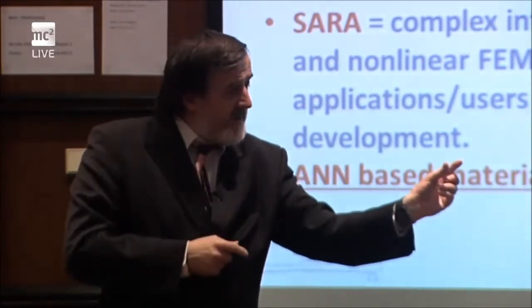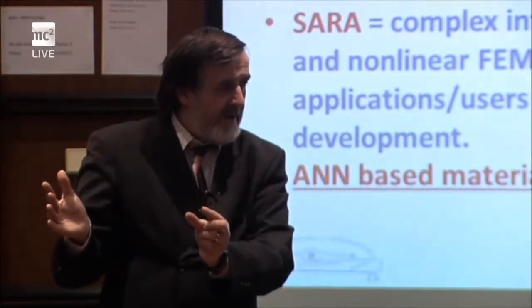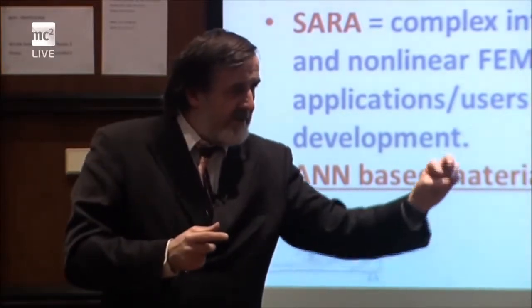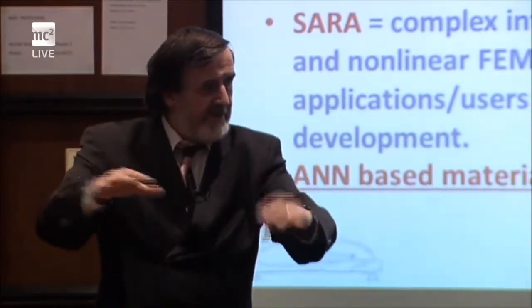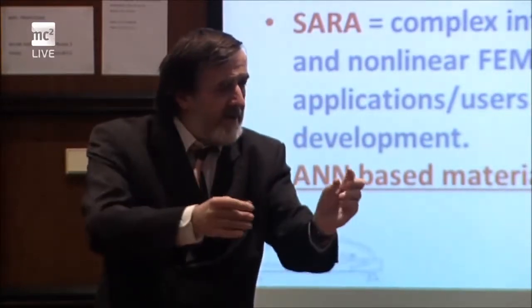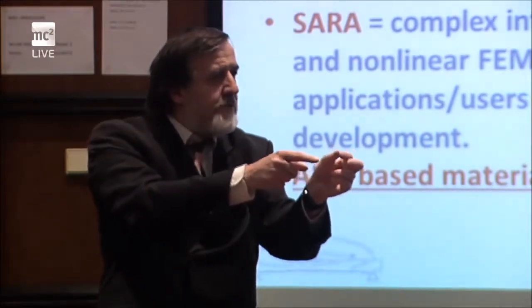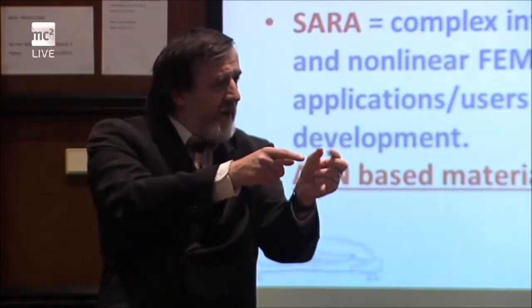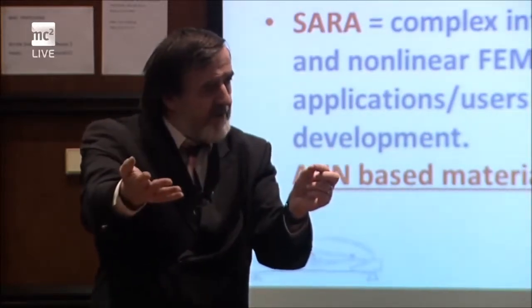If we take, let's say, the nominal value of stiffness, so there is an undamaged structure. And now these stiffnesses we change randomly to imitate so-called damage. If I change the stiffness somewhere in the beam, it's supposed to influence eigenfrequencies and eigenmodes, right? So it's happening, really, in the model.